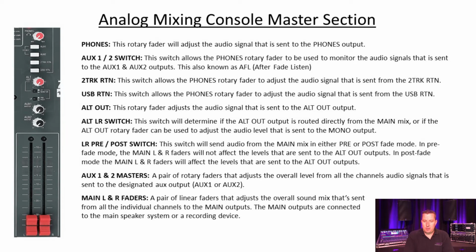This switch will send audio from the main mix in either pre or post fade mode. In pre-fade mode, the main left and right faders will not affect the levels that are sent to the alternative outputs. In post-fade mode, the main left and right faders will affect the levels that are sent to the alternative outputs.